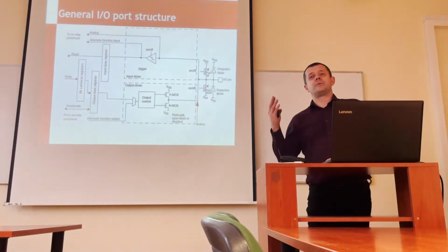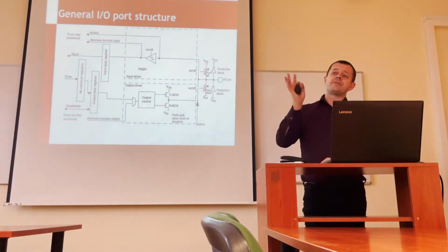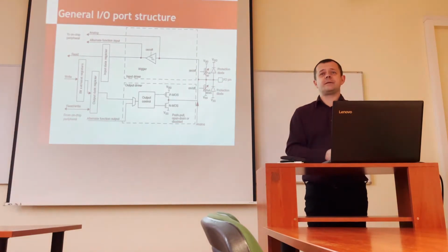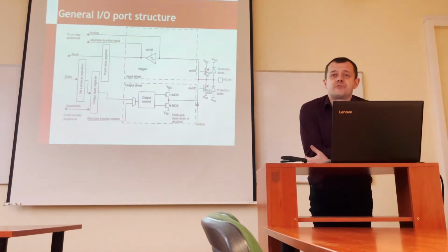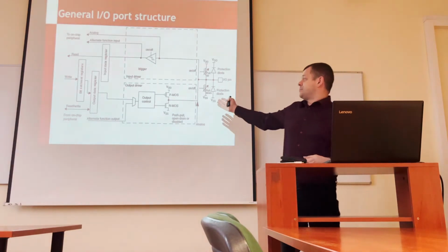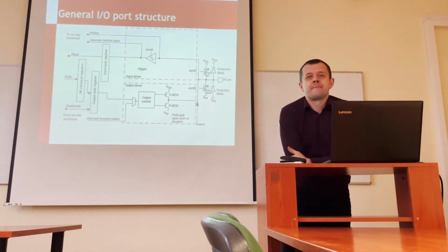But normally we talk about 10 milliamps, 20 milliamps, sometimes even 100, but be careful here, 100 is not always possible, so it's quite rare. Normally we have 10 milliamps, but still, if we take into account that we need a couple of microamps to drive one input, then it means that we can connect any number of inputs to one output. What is limiting? That's a good question to you then.